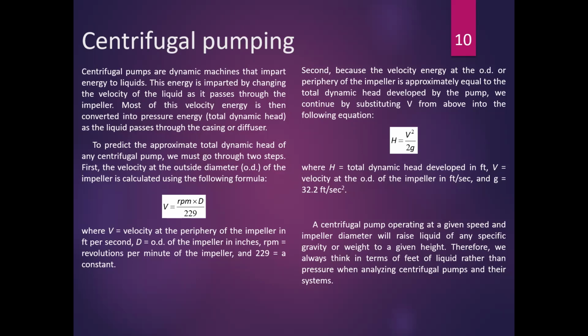So a centrifugal pump operating at a given speed and impeller diameter will raise liquid of any specific gravity or weight to a given height. Therefore, we always think in terms of feet of liquid rather than pressure when analyzing centrifugal pumps and their systems.